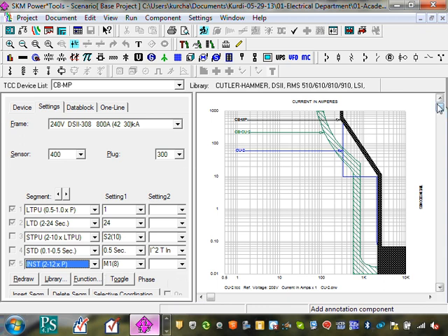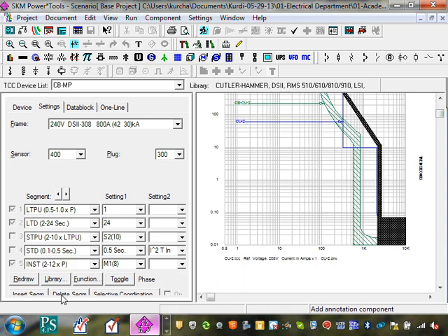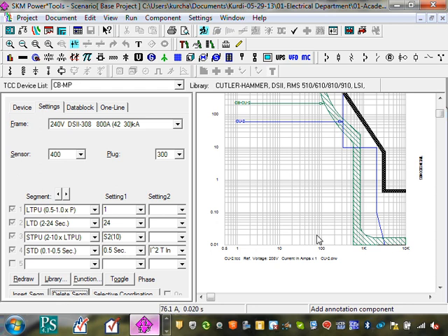Okay, where are we here? Okay, so delete segment. See what happened here? What happened to this curve? It went up. Now the short circuit is going to sit in your system 0.1, 0.2, 0.3, 0.4, 0.5 of a second. Right? 0.5 of a second, guys, is half a second. Half a second is an eternity. Enough to burn your equipment completely.